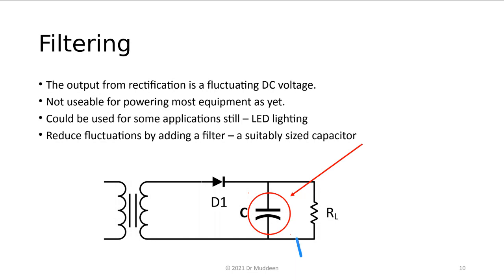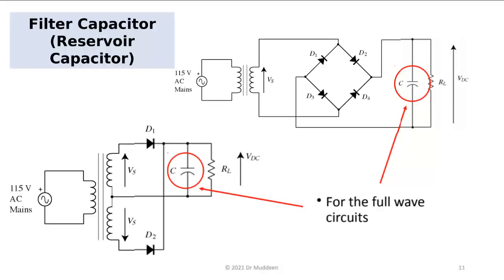So here, technically speaking, on the diagram, should be ground. And on the full-wave rectifier side, here should be ground, and here should be ground. Okay, so you could add that to your slides as well, and notice where the capacitor is in both cases.